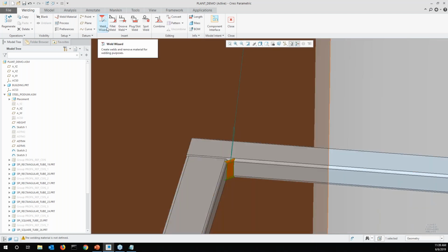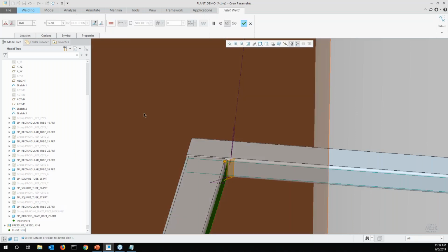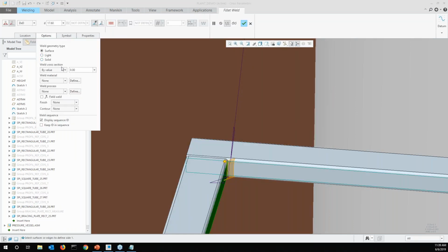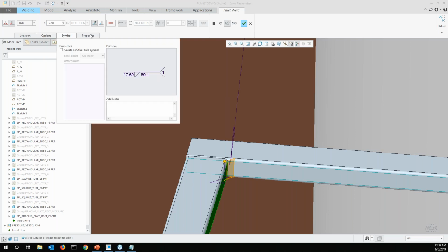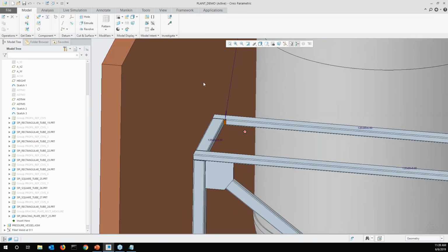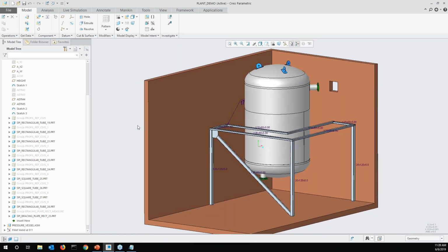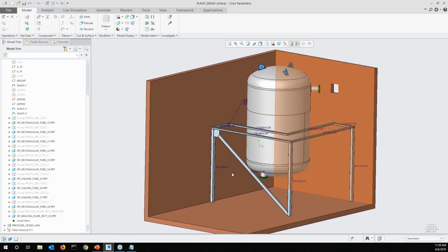Okay. And another thing I want to show, just because I've seen there are a lot of questions about the weld feature here, is you can add materials to them if you make them a solid. So if you go to your option to make them a solid and define what your cross section is, your material, your process, any of that, modify your annotations, and then have that all be pushed to your drawing environment and simulations or comprehensive mass analysis, all captured within the assembly here.